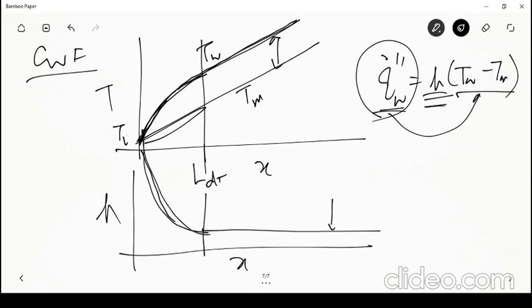So if I plot H as a function of x, the same LDT, it becomes a constant, and before that it starts from infinity and comes here. So this is the same variation that you have, but now this number is 48 divided by 11. Okay, so that is the number that you get for constant heat flux, which will be something like 4.36.